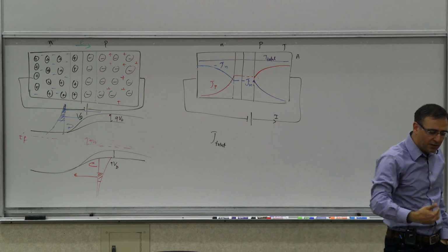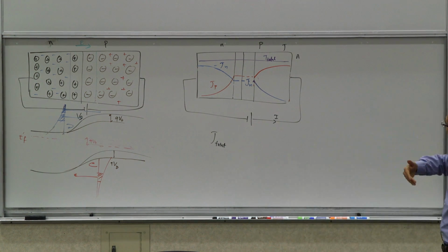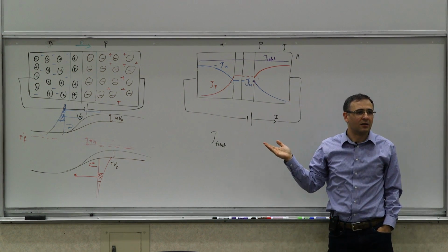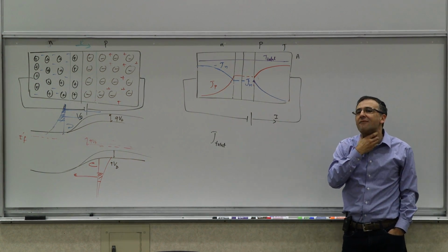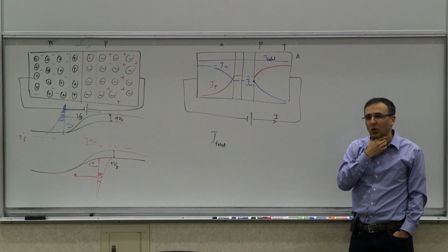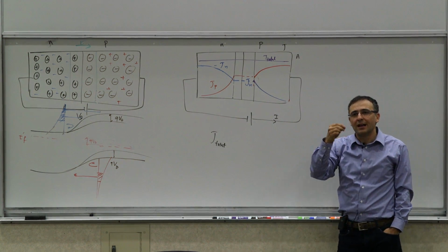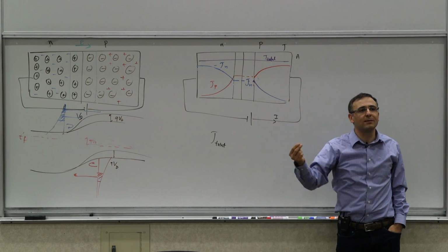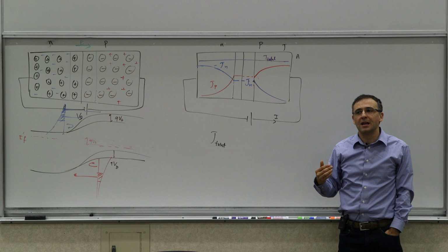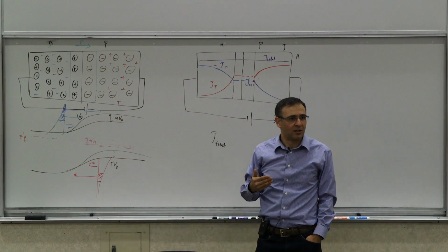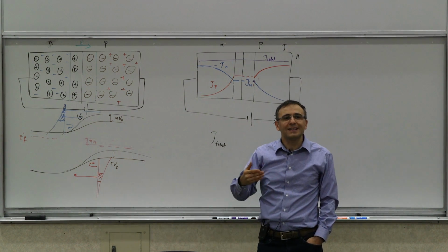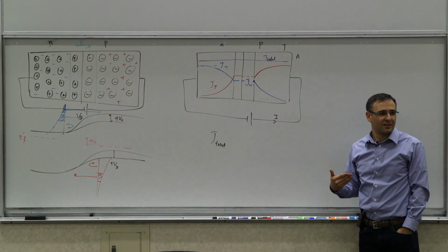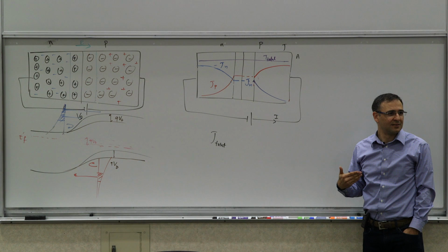Because if I let the minority carriers just propagate, eventually most of them, and eventually all of them, will recombine. So you have lost that leverage over them. You want them to be used in a different location. So you want to absorb them into a place where you can manipulate them without a significant amount of recombination. So you want to get them into a region where there are majority carriers again. Right? Does it make sense?